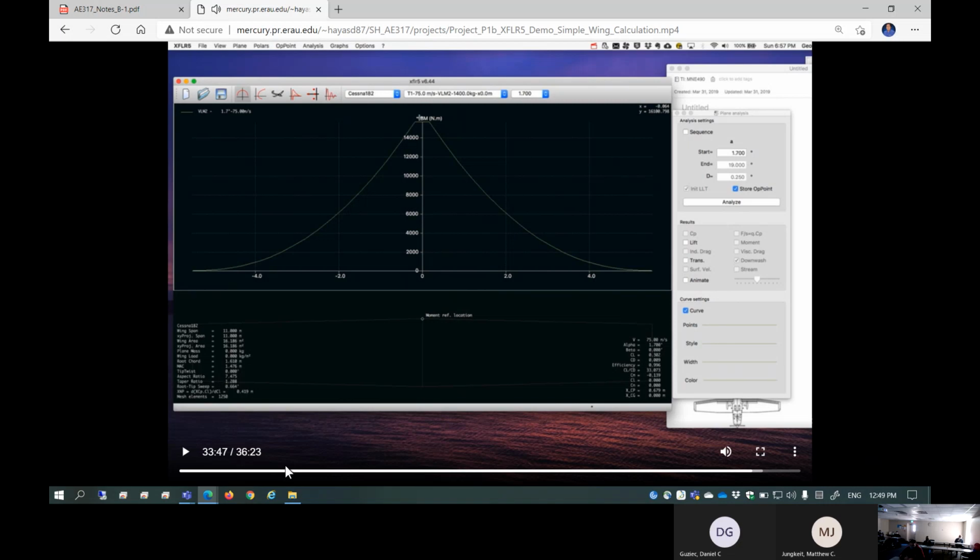So this is basically the wing loading based bending moment. So when you attach your wing to the fuselage, of course, you need to have a strong enough attachment of the wing to the fuselage. So this actually comes into play at a later stage of your design process, when you start thinking about literally manufacturing this airplane based off of the X-foil analysis. So this is the bending moment. You cannot use something like plywood here. You have to use something like an aluminum bar. You have to design those manufacturing processes.